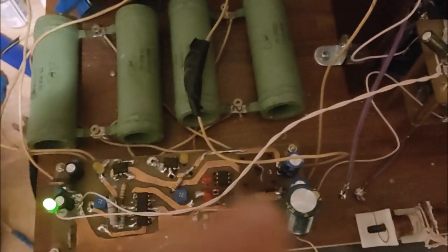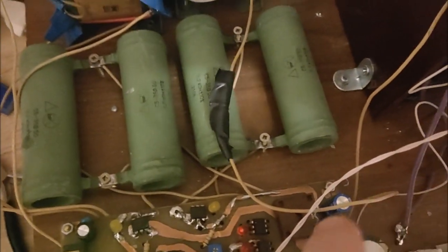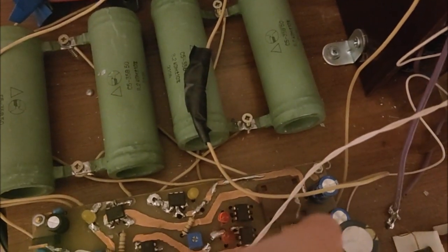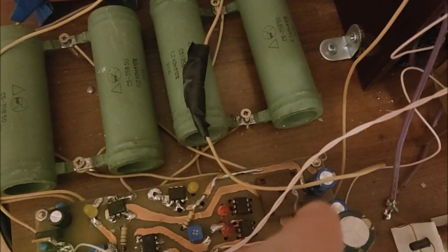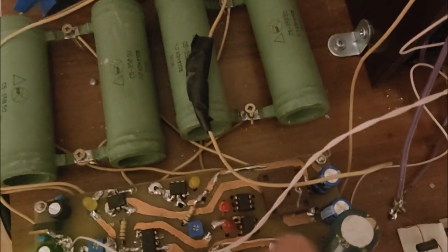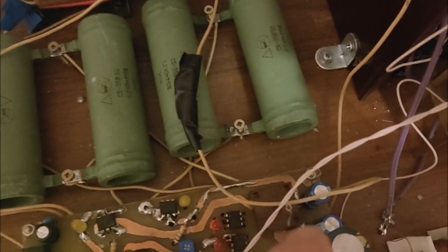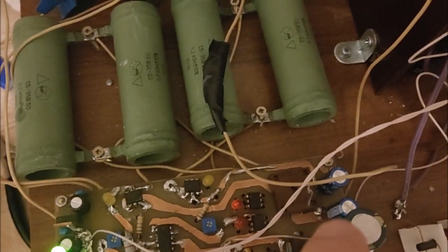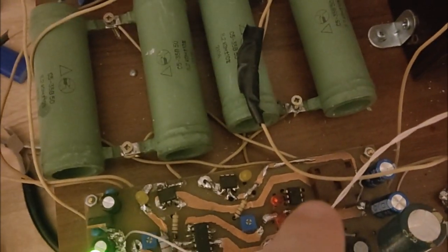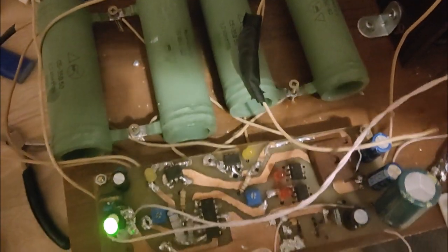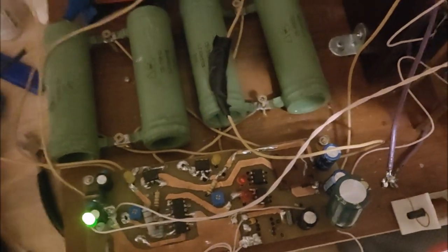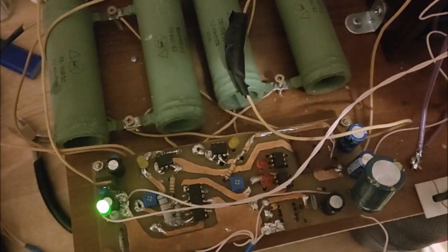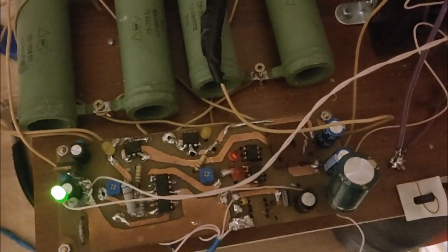Here are also some auxiliary diodes which ignite when the voltage on capacitors is close to its maximum, so they are indicative diodes. And these little capacitors are shunting capacitors in the positive and negative branch in which voltage is controlled. They are 10 microfarads and 450 volts each. And here is a diode bridge which I use as rectifier. It is divided into two parts and serves as a rectifier in each branch.